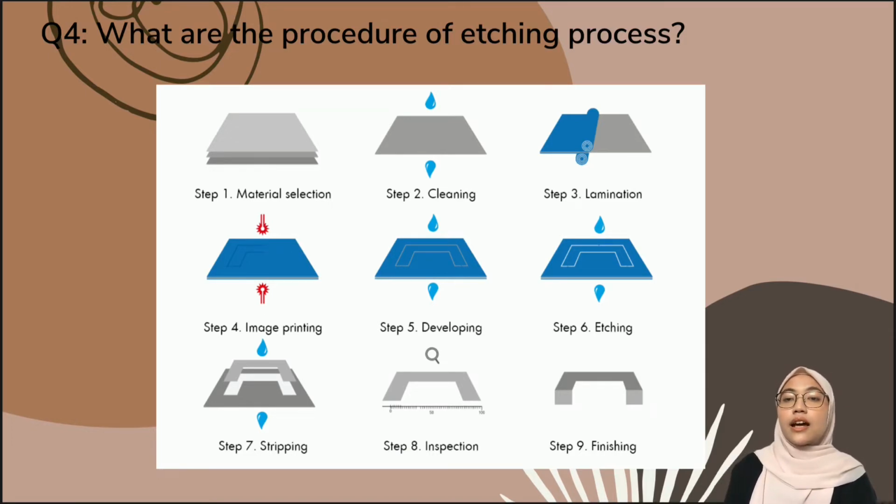Chemical etching is highly advantageous and offers many benefits. This process does not use mechanical forces unlike stamping, which subjects sheet metals to extreme pressures, nor does it put thermal stress on the cutting edge unlike laser cutting. Alongside this, chemically etched parts remain flat, firm, and very stress-free, leaving the material properties unaffected.